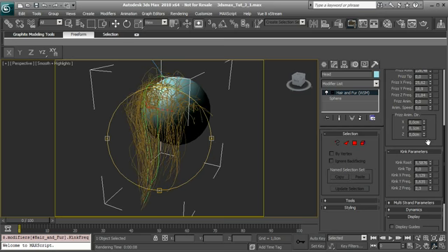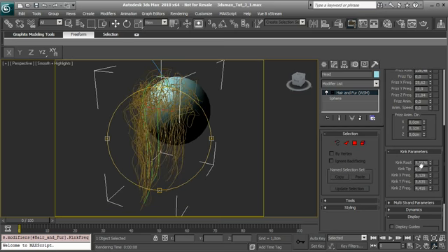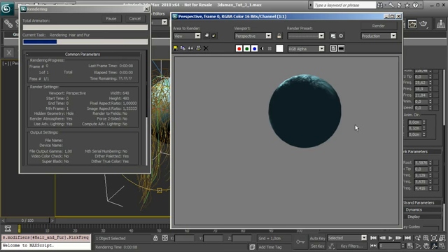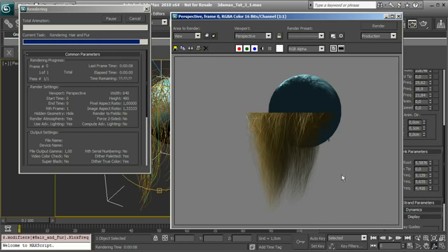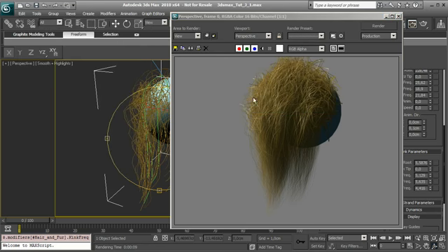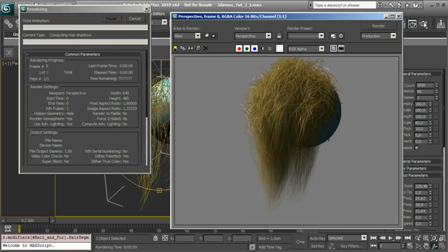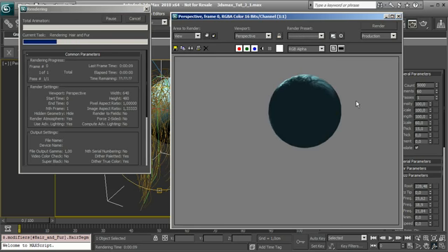So with more frequency we can have more and more chaos, but for example on this test you can see that when I try to render it, we have not so much detail for the hair, so we need more segments. You can see there that we have no segments to make this kind of render. So in this case we have to go back there and for example maybe use 16. Let's see if it's enough or not.